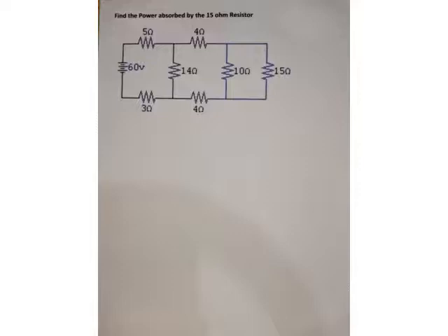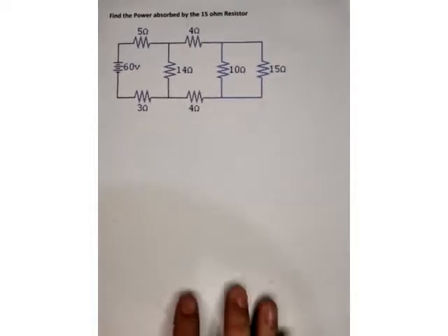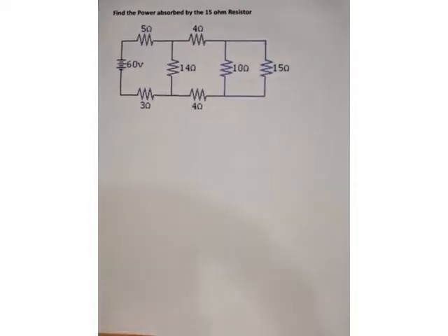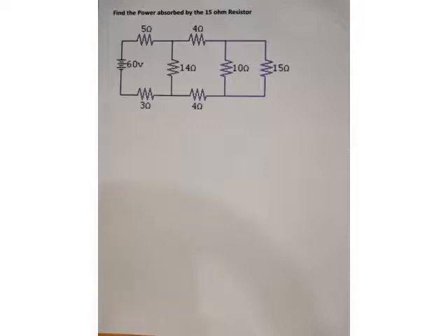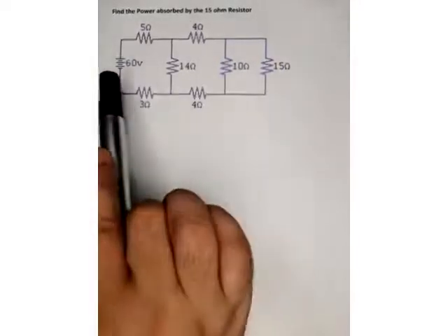Okay? Similar to what we have discussed before, if we will only be using the series-parallel method or combination in solving a network, first, there should be only one source, which is also the case in our given circuit. Then next, we need to find the R equivalent to get the total current. It's always like that: find the R equivalent and then the total current. So, we'll start with the resistor farthest from the source.